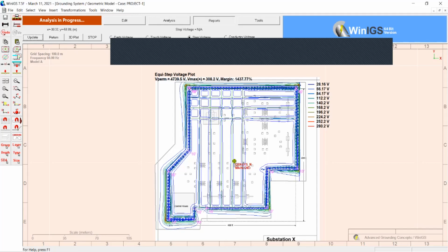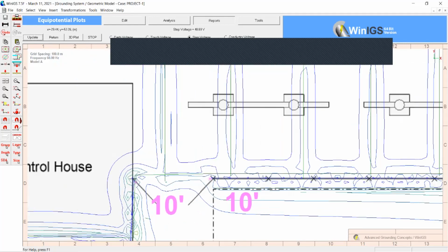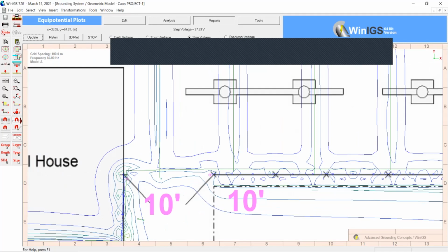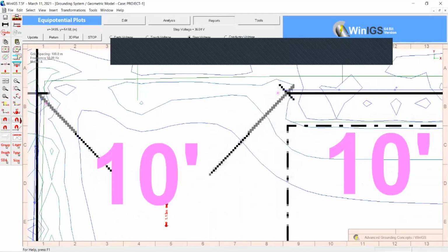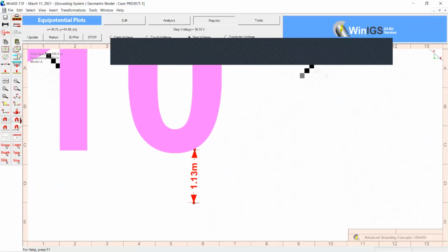So definitely you'll take the reading close to the gate, because that's the area where the possibility of the personnel to walk is the highest. Okay, so in my design, here is the gate. So you will take 1 meter, 1 meter. Okay, 1 meter, and I'll show you what you'll do. So you'll put this 1 meter distance in 5. You'll find 5 points outside of the fence.